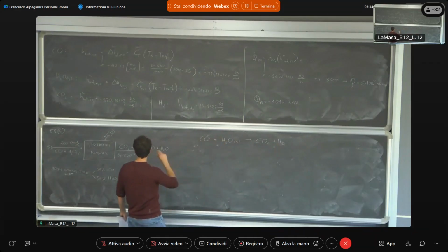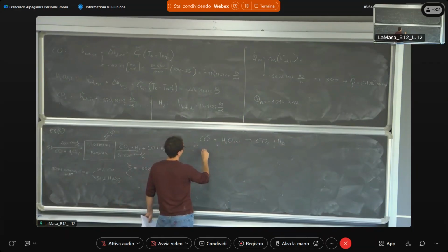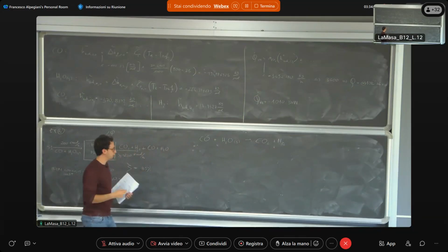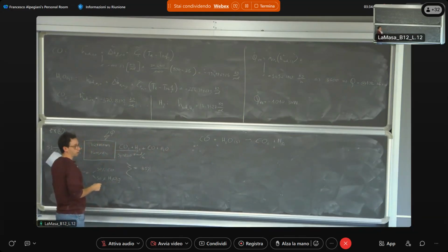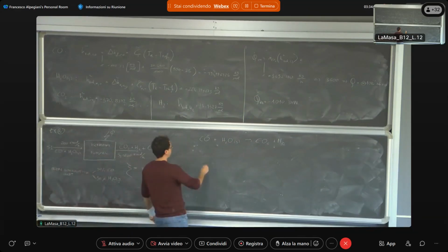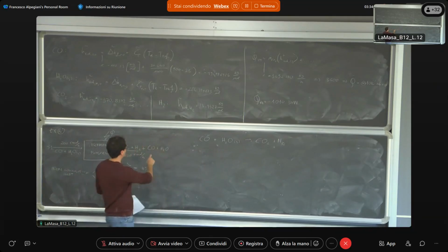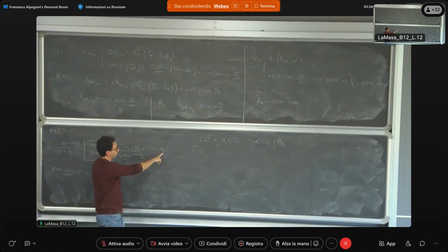Essentially, what you obtain at the exit, since only 85% of the 100 kilomole/hour that you have before reacts, is a composition in which you have 15 kilomole/hour of CO and 15 kilomole/hour of H2O that did not react.